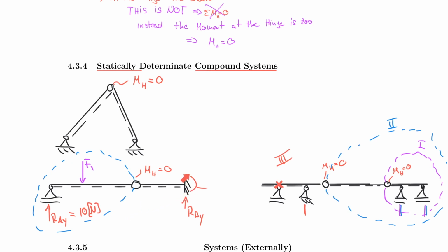And likewise, this moment here, MA about the z-axis, has to be in equilibrium with everything that acts to the left of the system. There's no exception to that. Again, I see students often initially being confused by the hinge here, but the trick is, once you've figured out one unknown, the hinge does not matter for now. At least as long as we talk about support reactions. Later on, when we talk about internal forces, of course it has an impact. But again, we'll talk more about that later. So for now, don't worry about this.